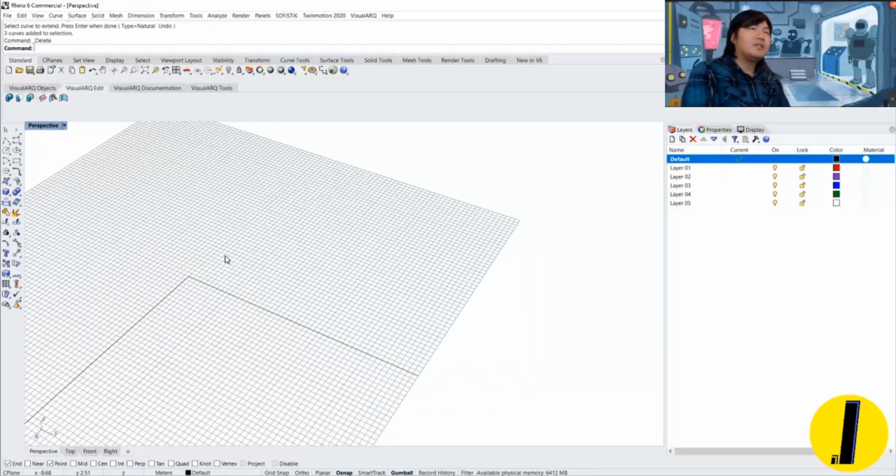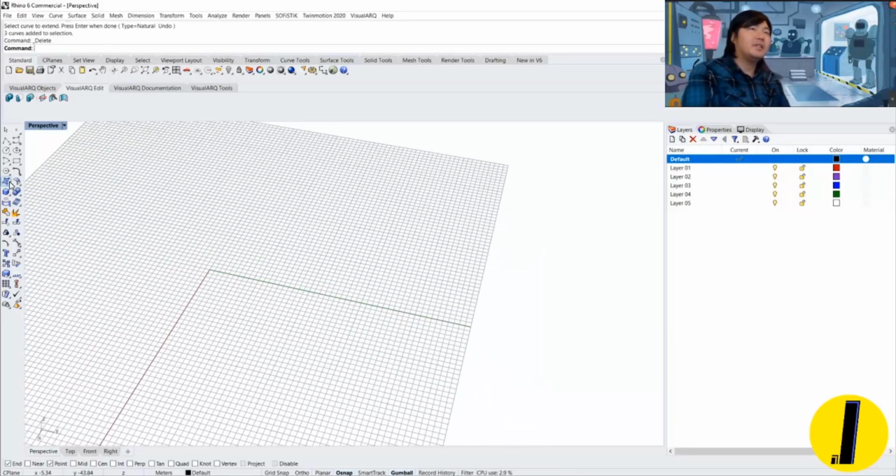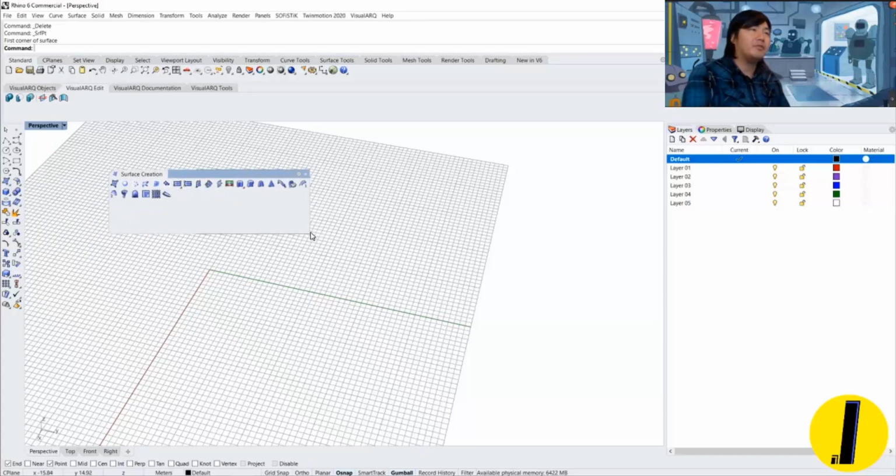But today what is going to be interesting for us is of course to draw surface. So I'm just going to hold my mouse cursor left button for a couple of seconds, and then you can pop up this extra toolbox that we can extend the function. And the first one, the command is called surface pt. So that's the whole command word. So you can use surf pt.